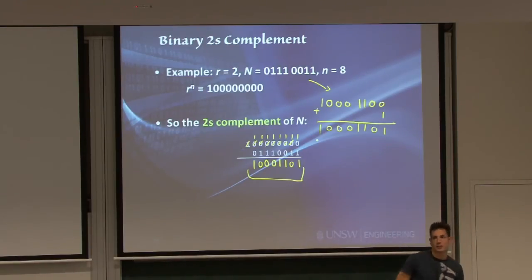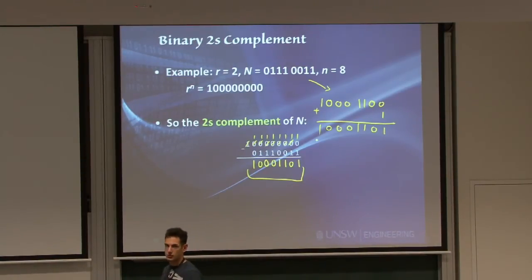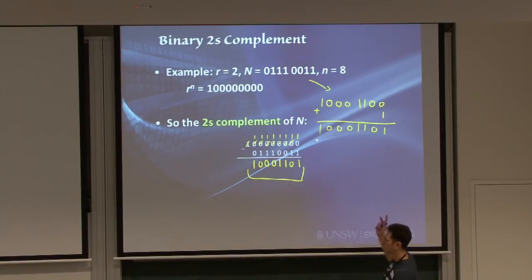So whenever you're asked to take a two's complement of a number, and you will see, especially in the next lecture on Friday, that we will take tons of two's complements all the time, the easiest way to do it: invert all the bits, add 1. There are other ways to do it, by the way. You may have heard or you may hear about other ways. This is the method that I like. It works. If you prefer another method, go for it, as long as you get the right answer.